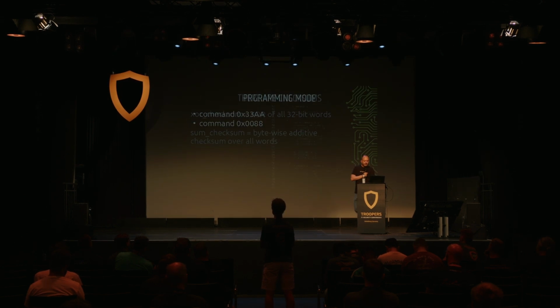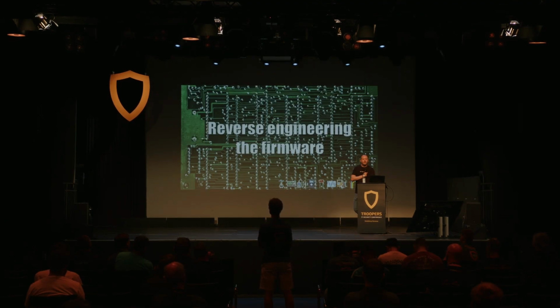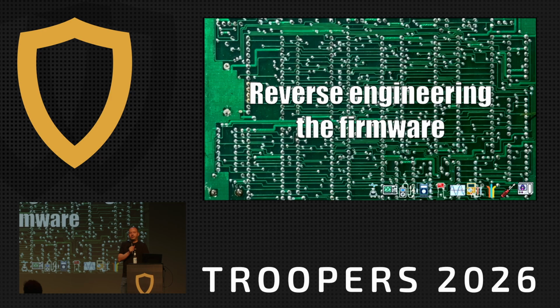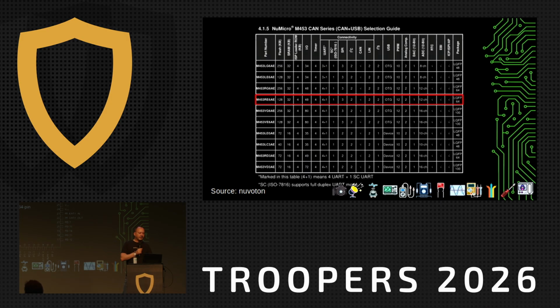The reason why I went through the software up until the MCU actually modulates the signal is to make sure that it's not done on the MCU. We verified that it's not done in firmware, and we verified that the data goes out of the relevant pins of the MCU, right? So that's the data that comes out.